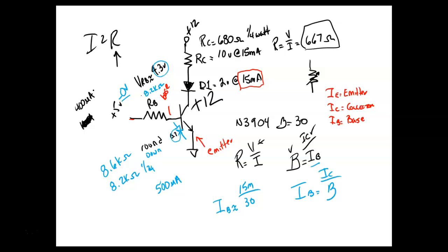But for a high, for a digital circuit, these are nice big digital circuits too. So when or if you take digital electronics, you'll learn about the specifications on the integrated circuit. So 400 microamps, we couldn't do much with 400 microamps, but we could run it through a transistor as a saturated switch, and now we can do a lot, right? You understand? So I could get up to 200 milliamps out of this thing.